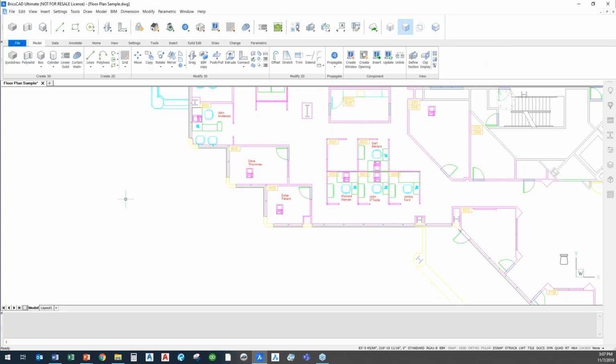When I'm out here in space, so my cursor is just floating, all I have to do is right click. And you see it gives me this little pop-up. This is the quad tool. And all I have to do is move my mouse over it. And it gives me, broken down into categories, all of the basic drafting and design controls that I need in this space. So I have all of my basic drawing tools right here. I can just say, hey, I need a line, and I can draw my line from here to here. There you go, I draw a line.